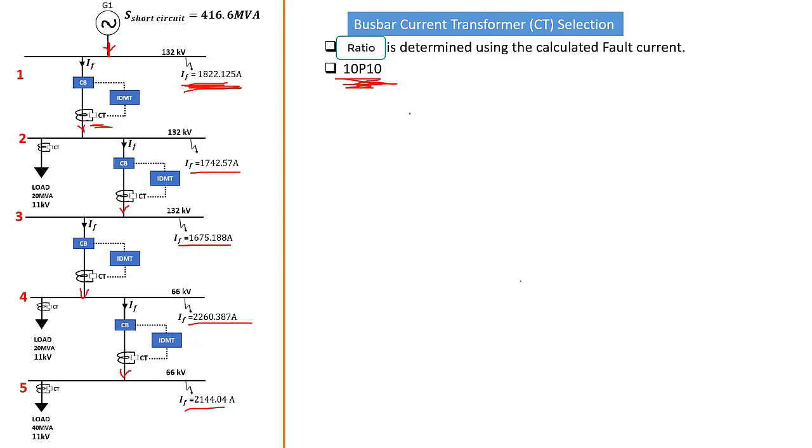And so that 10% margin of tolerance will actually ensure more reliability for your selected current transformer. And reliability is very important because you don't want to be sending false triggers into your relay coil, and that's going to be tripping your circuit breaker even if there is no fault. So you need a reliable system. So the margins of accuracy are important.